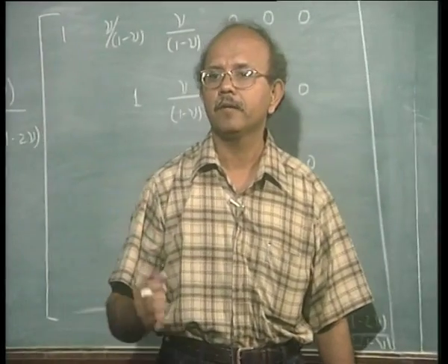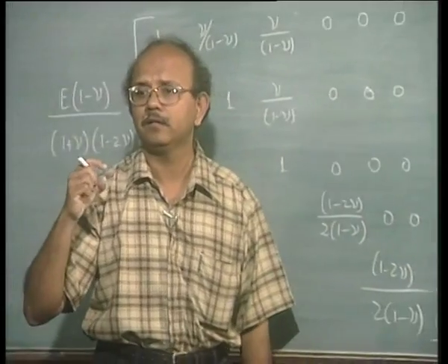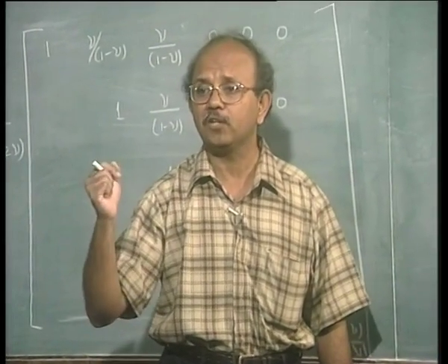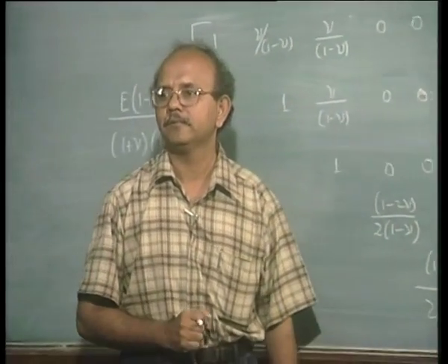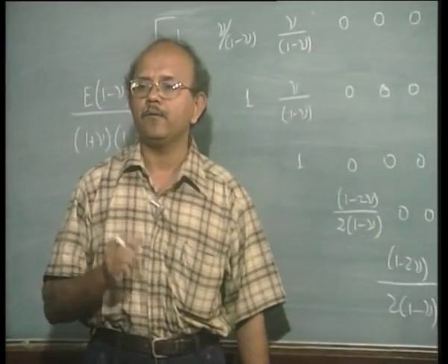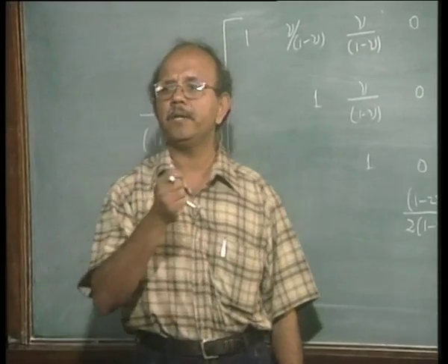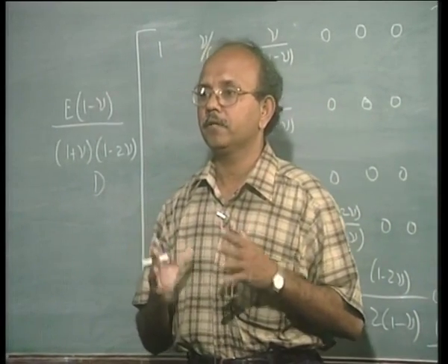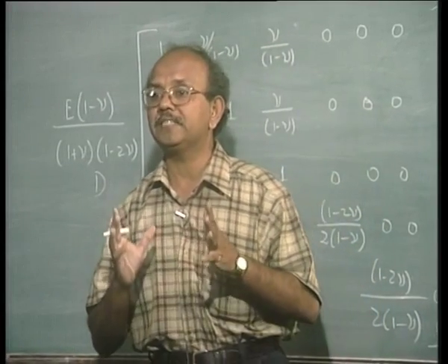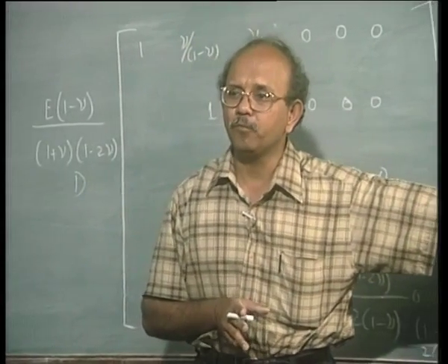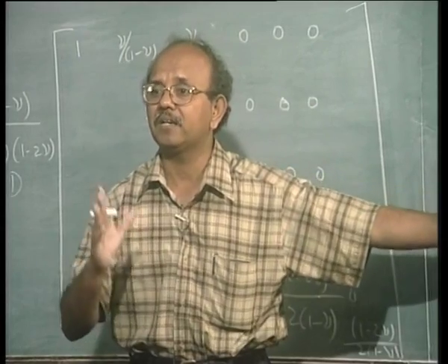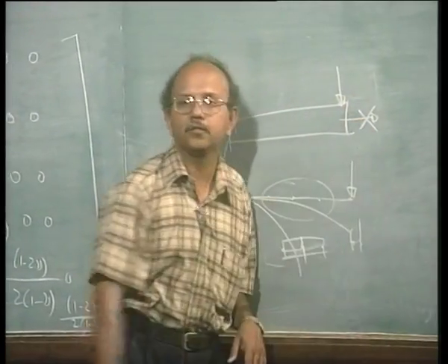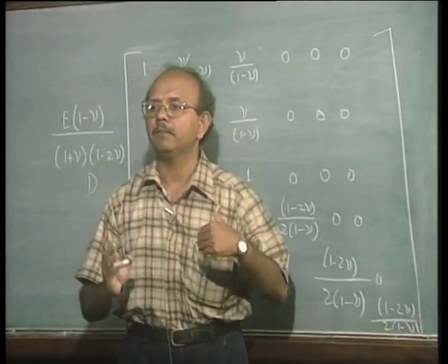So in other words, how many degrees of freedom do I add? 2 more, because there will be a displacement as well as rotation in directions perpendicular to what I had initially for a 2-dimensional case. I want to introduce one more thing. The beams that you saw may also take some tensile loads. So if it starts taking tensile load, then this beam theory that we have studied so far cannot take it, because beam means bending, we know, and this cannot be simulated by a beam behavior.